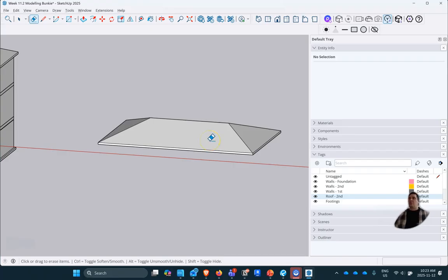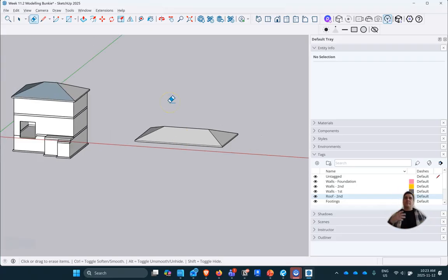And so that's how you can extrude those faces through to create a roof, or you can just draw those lines and find out where all those points intersect. So that's kind of two different ways to do it. And I will often use both methods, because if I find there's a roof that's really complex and I don't know how it intersects, I'll just extrude those faces through, and then I'll use that intersect tool to find where those common edges are. And if it's really confusing for you, what you could do is do the different planes as different groups, just so that you can extrude them through really nicely.